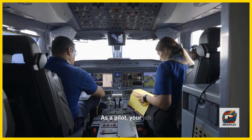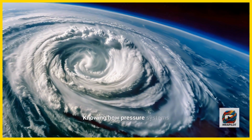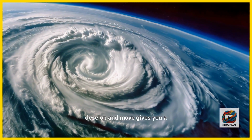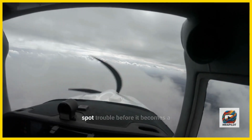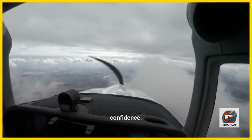As a pilot, your job isn't just to react to weather, it's to anticipate it. Knowing how pressure systems develop and move gives you a huge advantage. You'll spot trouble before it becomes a problem and adjust your plan with confidence. High-pressure systems bring the best flying weather, but may trap pollution or fog in valleys due to temperature inversions. Low-pressure systems bring dynamic, challenging conditions, but also the chance to build valuable experience if managed properly.